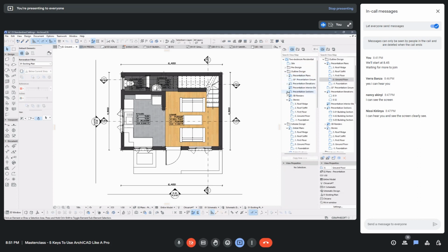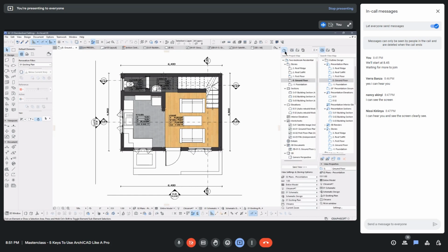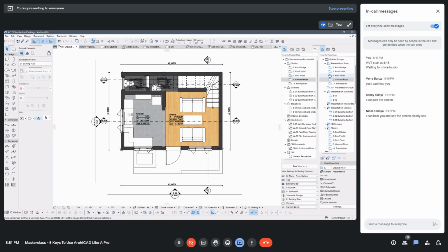As you can see, the difference between the project map and the view map is that the icons here are in black and the icons in the view map are blue. If you look closely at this specific one, it has the same shape as the stories icon, but there is a small arrow. What this means is that we are cloning the stories viewpoint to create a view.